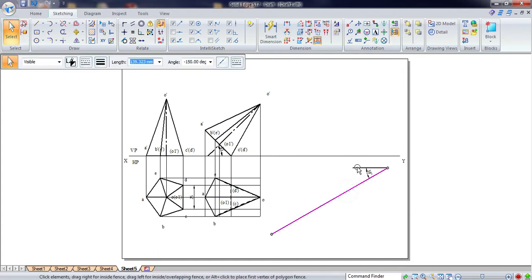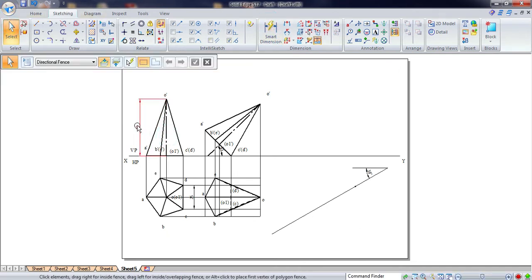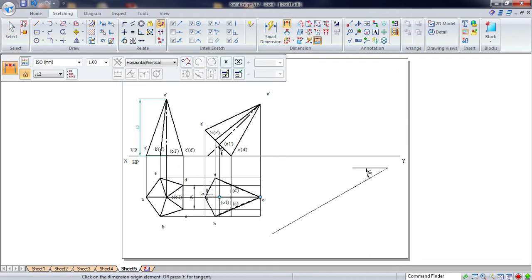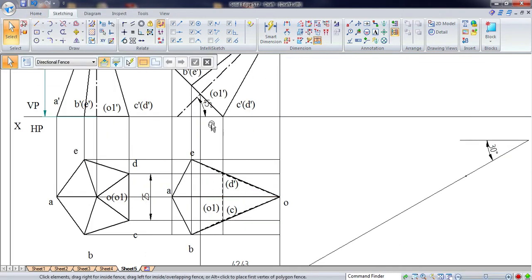Now again, these are all construction lines, 0.05. Go for the point, mark the reference point because this is a locus method problem. Again, first we need to measure the first axis length, which is given in the problem as 60, and after this we need the distance from O to O1, which is coming out as 42.426. Make sure that it is O to O1.